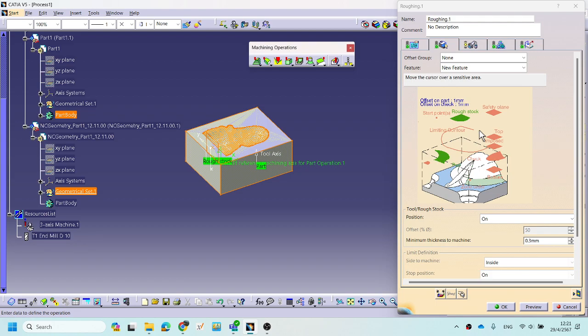The tool is not touching the workpiece, not the finished part, right? Not yet, because it's offset from the finished part. The next step, the offset should be reduced, and until finish, the offset should be zero. Okay, it starts.